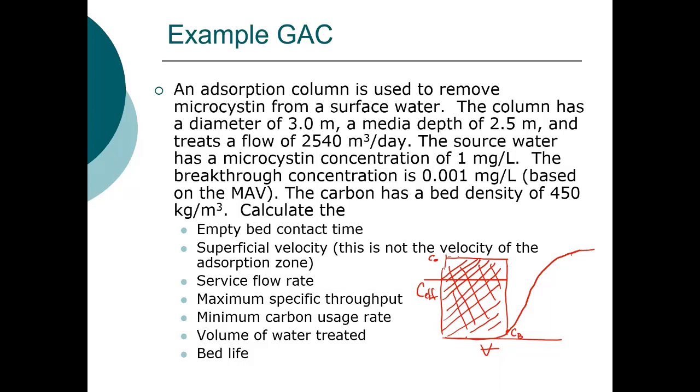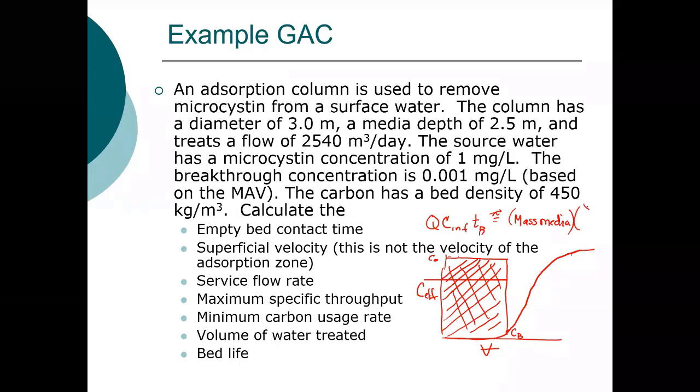So this is approximately equal to Q times the concentration in the effluent times the time to breakthrough. And that is approximately equal to the mass of the media times X over M at C influent. So the X over M value at the influent concentration.